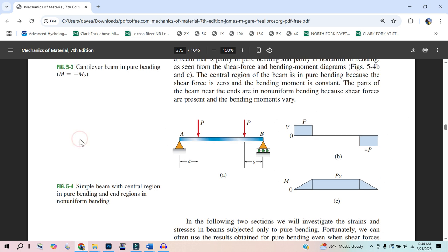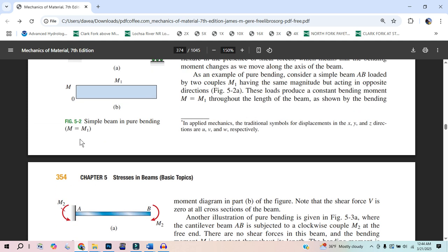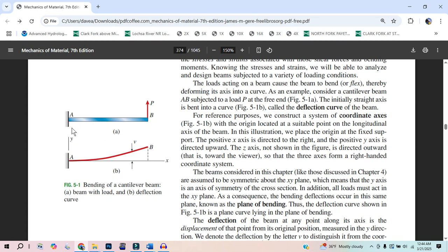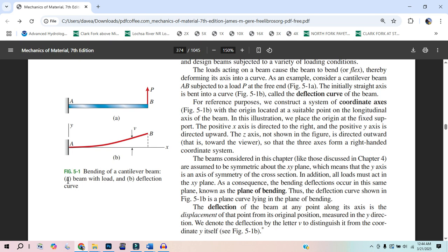Again, that was just a thorough way to go over it. I just said this should have had a moment diagram and a shear diagram, because that was another red flag on mine. For a second there I thought, there's no shear in this, but no, there's shear, and then there's moment. Because the shear is a constant, the moment is a linear function.